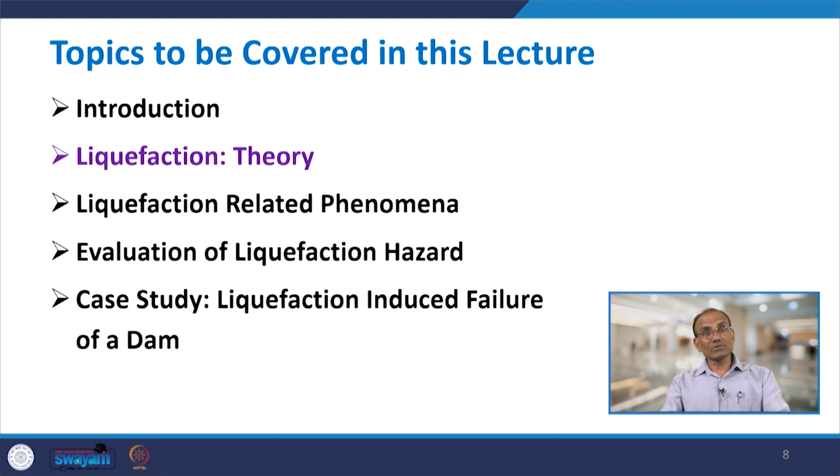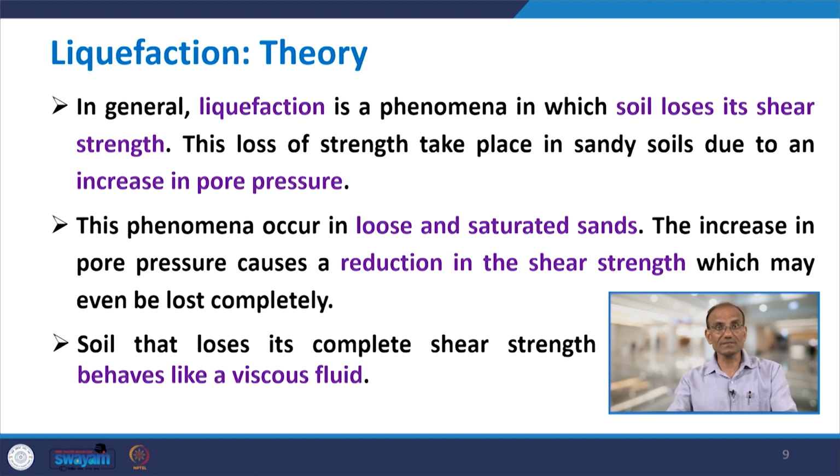Now, coming to the theory part of liquefaction, what is liquefaction, how it occurs, let us discuss that in the next few slides. In general, liquefaction is a phenomenon in which soil loses its shear strength, because when we talk about soil, shear strength is the most important property of the soil, and the loss of this shear strength takes place in sandy soils due to increase in pore water pressure.